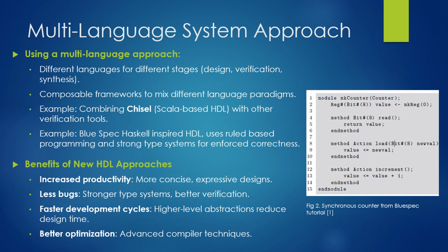optimizing circuit layouts. Chisel, a Scala-based HDL, as mentioned in the paper, is a hardware construction language that builds on functional programming concepts. The HDL generates Verilog code while also providing higher level abstractions than older HDLs. It also improves modularity and reusability, so larger scale hardware designs can be more manageable.